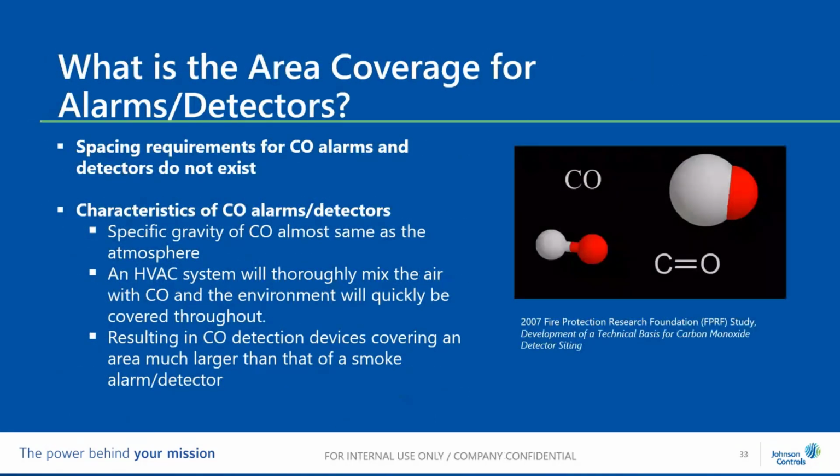So what's the area of coverage for these alarms and detectors? There are no spacing requirements for carbon monoxide. Again, it's a big myth out there that people are running around saying it's 30 feet, it's 50 feet. And there is nothing out there.